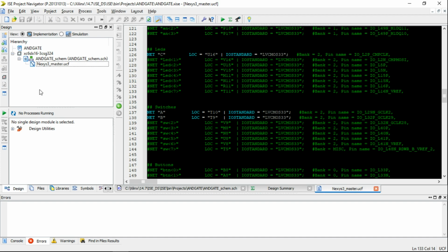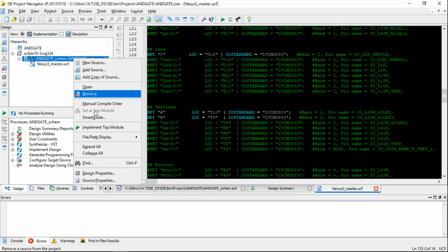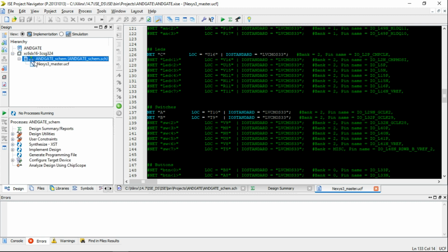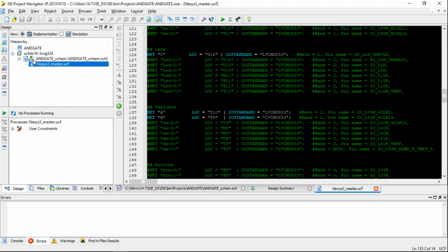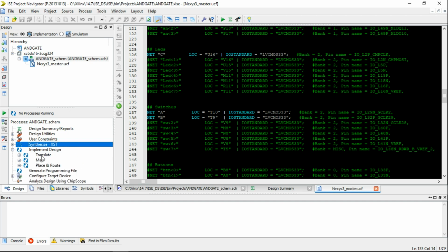Now to program the board, what we do is select our top module. Notice it has this symbol here, the 3 chip things. Now, I would like to synthesize my design, then implement it, which means mapping it to the board and stuff like that. So this is translating it to lower level language, mapping it and placing it and routing it to the board.